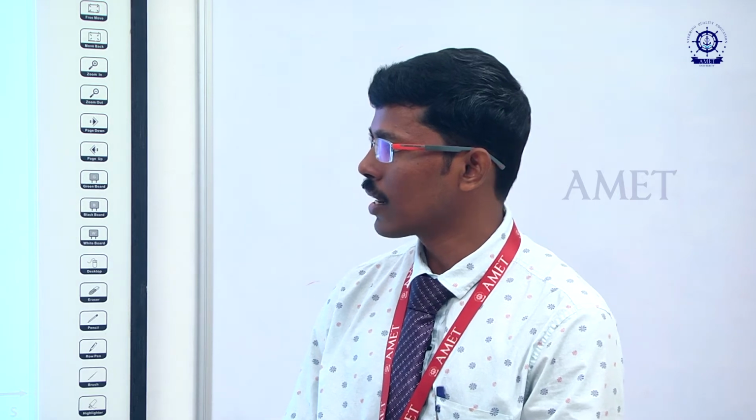Let us consider states 1, 2, 3 and 4, marked in the diagram, in the four component diagram of pump, boiler, turbine and condenser. State 1 is marked before the pump, state 2 is after the pump, state 3 is after the boiler, and state 4 is after the turbine. So, states 1, 2, 3 and 4 are clearly marked in the T-S diagram.